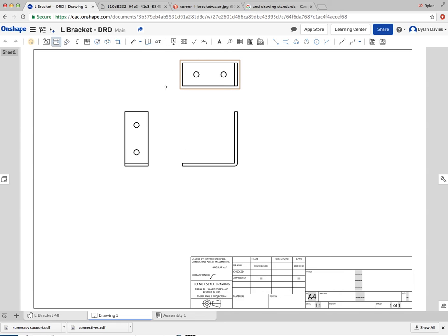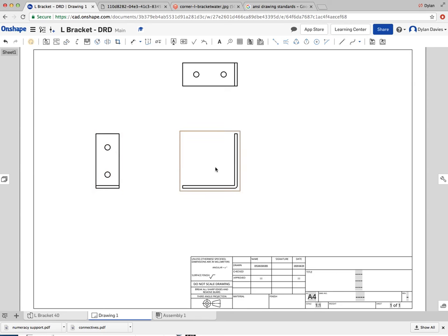Okay, so that's the basic view of third angle, and as I said, you can reposition these. So if I click off the toolbar there, and I can actually move these, and what I should now do is move everything else in line. So you can see that one moved in line. If it doesn't move in line, you haven't got yourself an accurate orthographic drawing. So I'm just going to bring this one down as well.